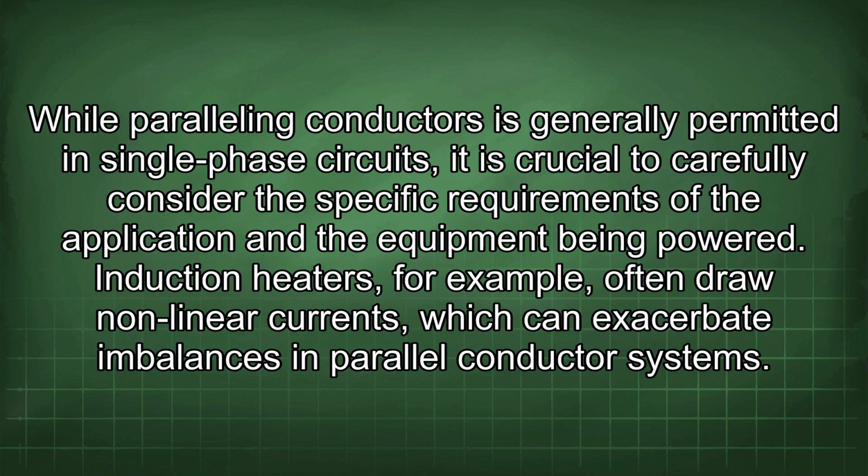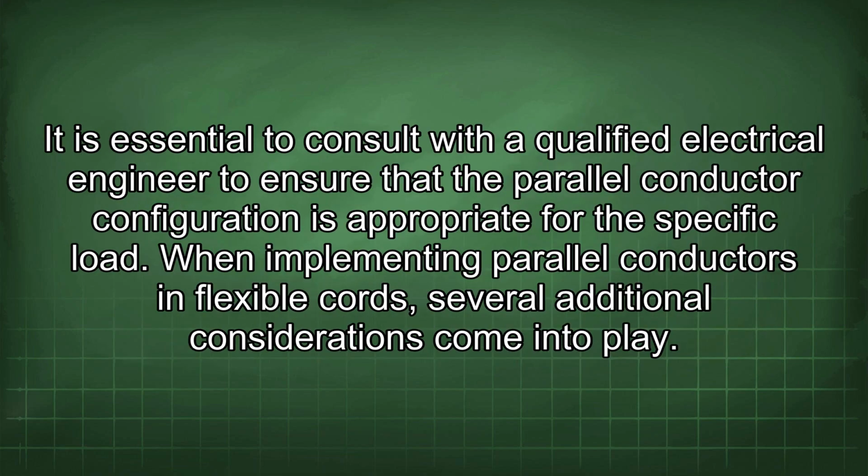While paralleling conductors is generally permitted in single-phase circuits, it is crucial to carefully consider the specific requirements of the application and the equipment being powered. Induction heaters, for example, often draw nonlinear currents, which can exacerbate imbalances in parallel conductor systems. It is essential to consult with a qualified electrical engineer to ensure that the parallel conductor configuration is appropriate for the specific load.